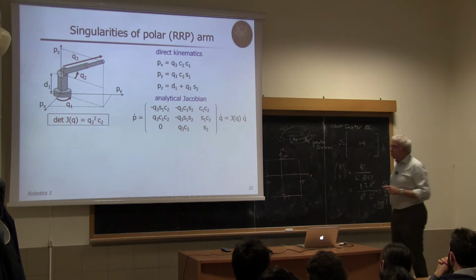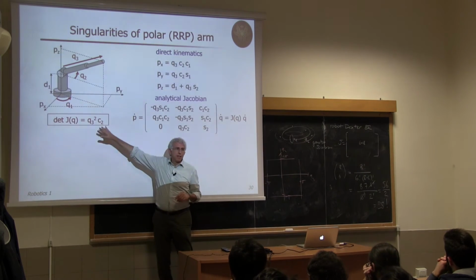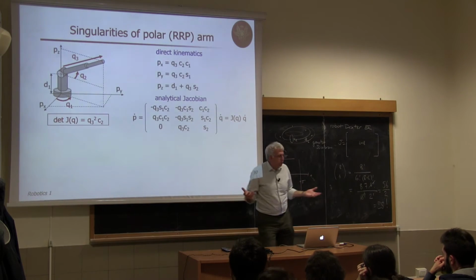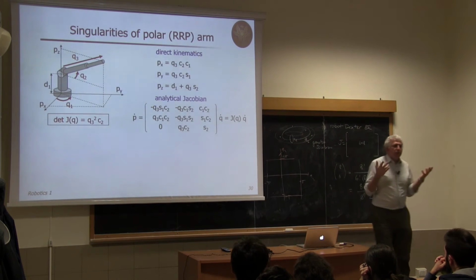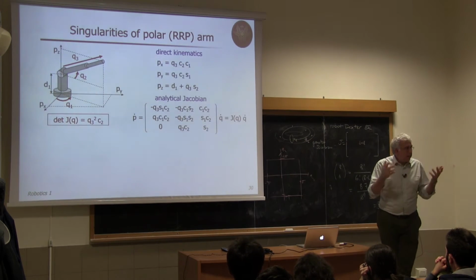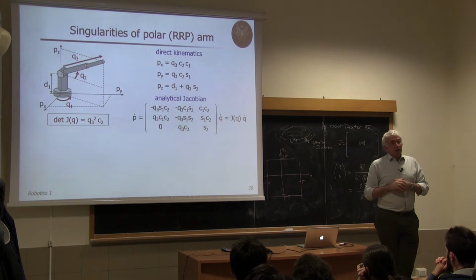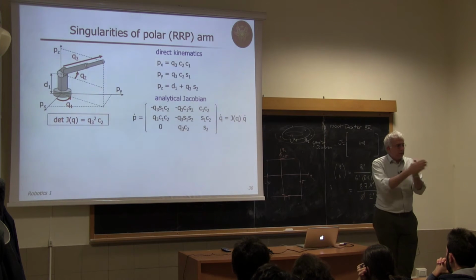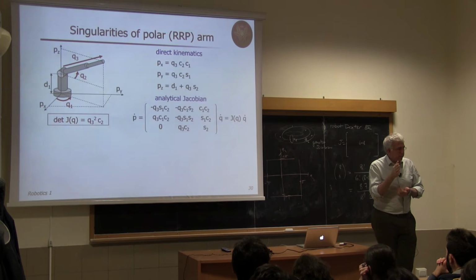Look at this. It's general, it's true. If there were Q1 here, then I could maybe find a value for Q1 where this determinant goes to 0. But Q1, what is Q1? It is the first angle in the Denavit-Hartenberg convention. Suppose that the first joint is revolute, so it's the angle θ1 between x0 and x1 seen around z1. But remember, x0 is arbitrary.